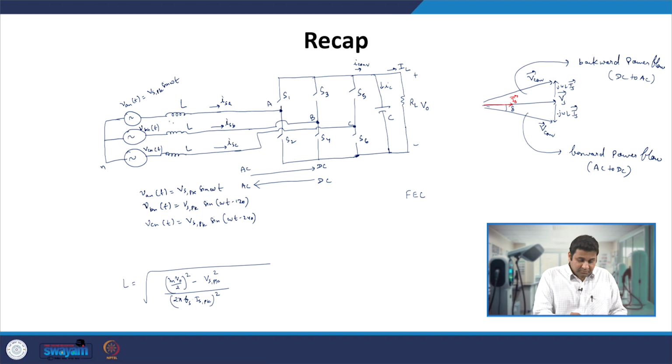That means this side voltage from the source is constant, however from the other side we can apply a variable voltage at a variable phase angle with respect to this source voltage, and that is when we can ensure that there is a current flow either from the AC source to the converter side, or from the converter side to the AC source side.